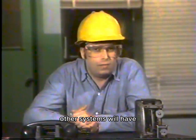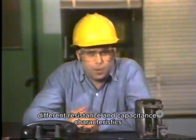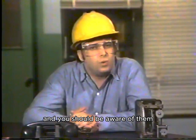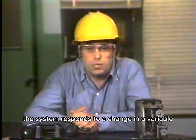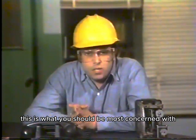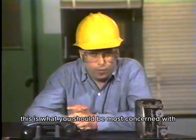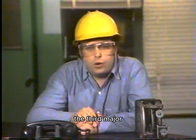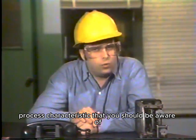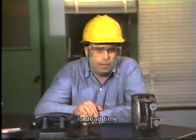Other systems will have different resistance and capacitance characteristics, and you should be aware of them because they will affect the way the system responds to a change in a variable. When you tune a system, this is what you should be most concerned with: how the system responds to a change in a variable. The third major process characteristic that you should be aware of is dead time.